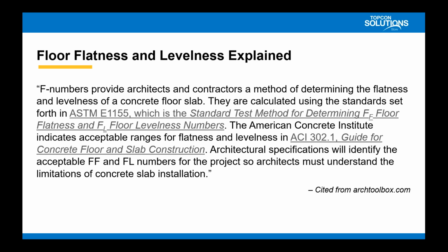Now, what is floor flatness and levelness? Well, the F numbers that we just talked about provide architects and contractors a method of determining the flatness and levelness of a concrete floor slab. Now, they are calculated using the standards set forth in the ASTM E1155, which is the standard test method for determining your floor flatness and levelness numbers. So I wanted to talk about this one a little bit in depth too.